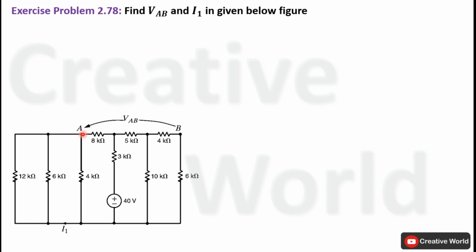In order to calculate voltage across these points, we should have the values of voltage across these individual resistances. And for the calculation of voltage across these resistances, we should have the value of current through these resistances. Right now, no current is specified inside this network. So first of all, we will simplify this network to calculate total supplied current. Then using that total supplied current, individual branch currents will be calculated. And these branch currents will be utilized for the calculation of voltage across these individual resistances.